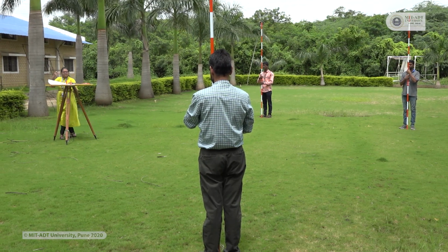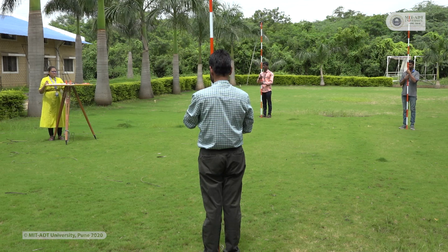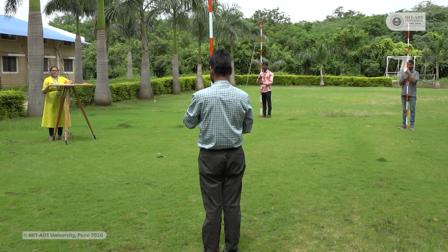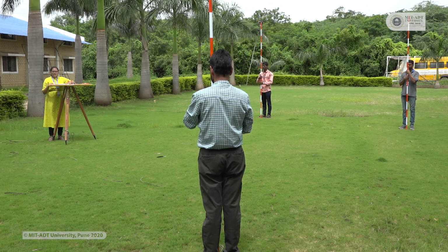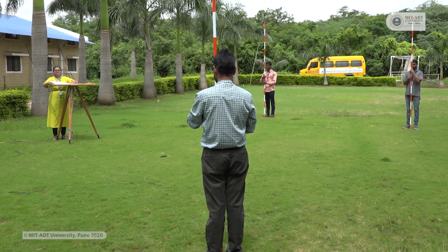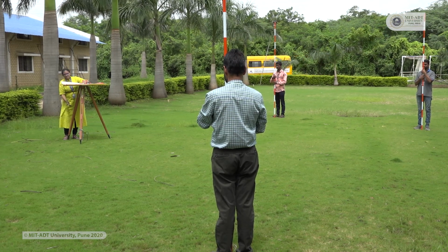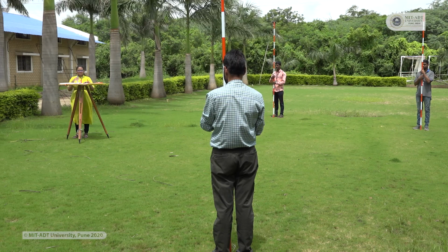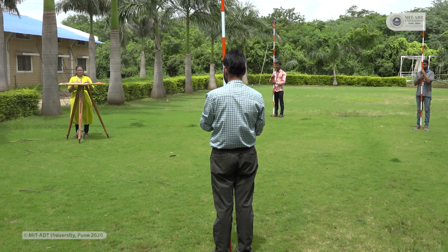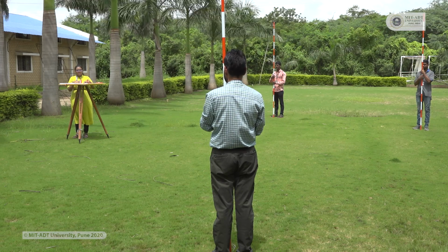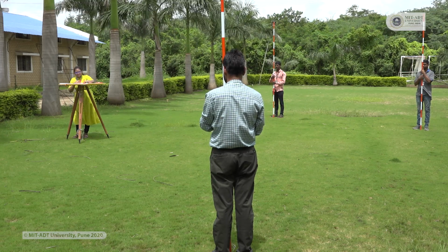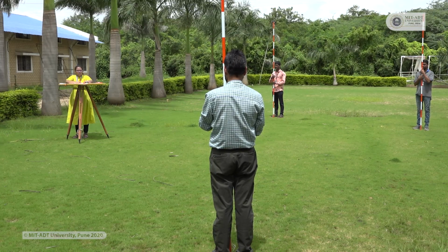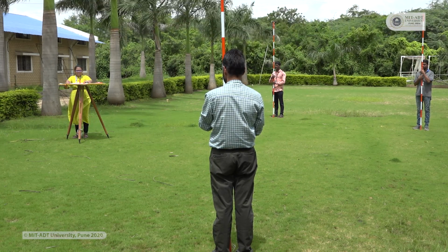Now we have already measured the distance between 2 stations, and that distance is 7 meter and 30 centimeters, which I have already marked on the paper. So now I will just adjust the center point of my paper with the center point of our station. So we have fixed the arrow at this center point. So after checking the north direction, we will adjust the line of sight from the station point first to the station point second. So I will just draw a line by using the alidade, and I will mark the distance on this paper. So distance is already known to us, that is the 7 meter and 30 centimeters.